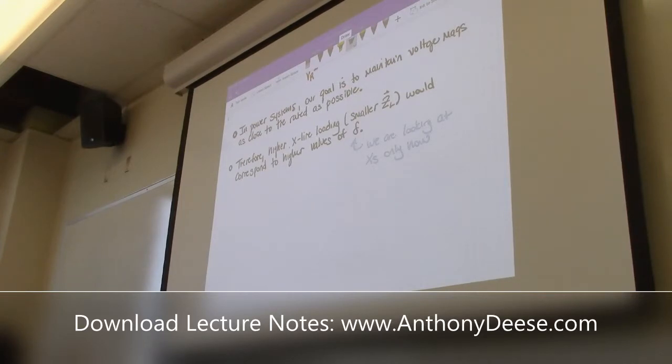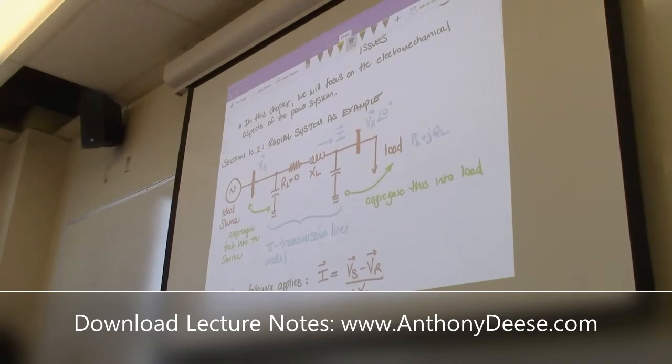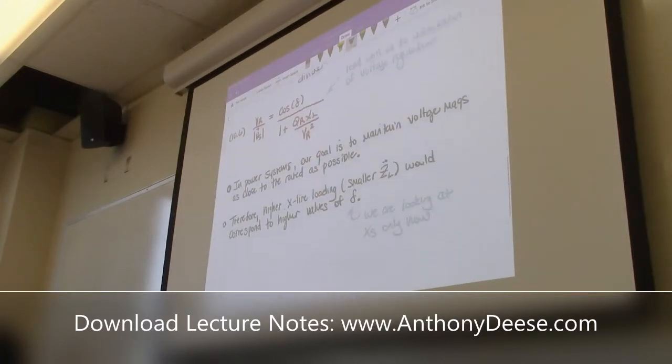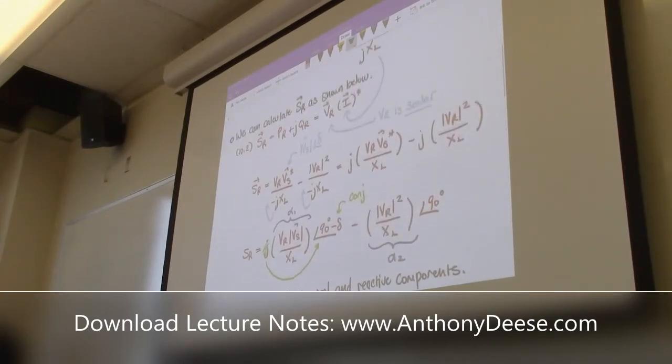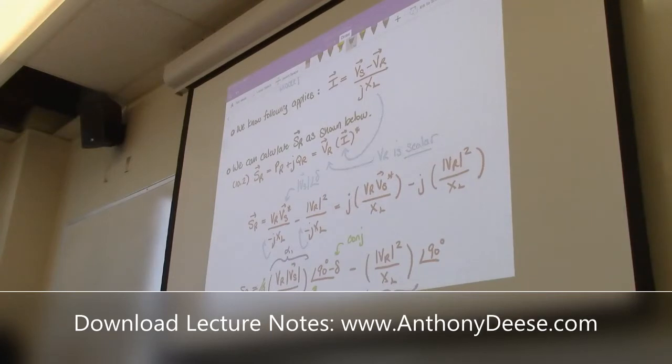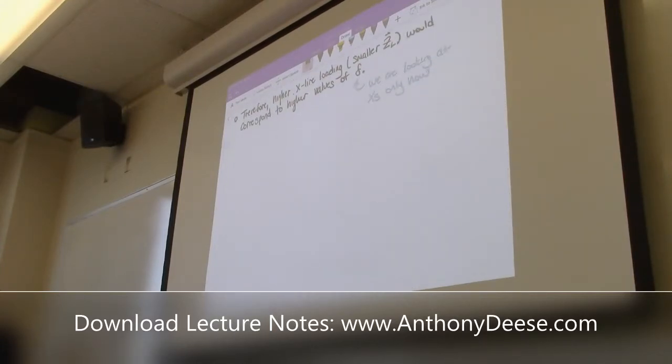And the reason why we're focusing more on delta as opposed to its direct effect on VR is because we're not considering the real component of the transmission line right now, right? If you go back to the circuit that we're using, for now, we're considering that the resistive element of the line is 0. And that would change the work that we just did because, if we were to include a resistance here, that would give us more terms in our analysis. Okay.